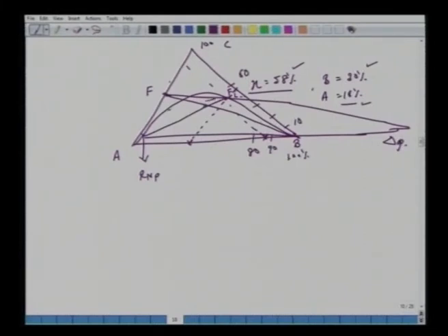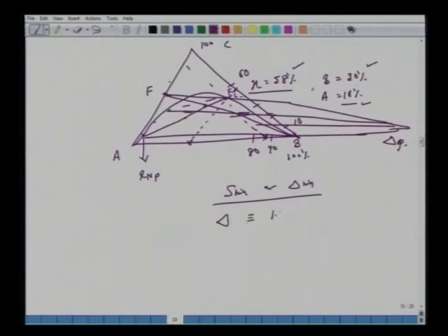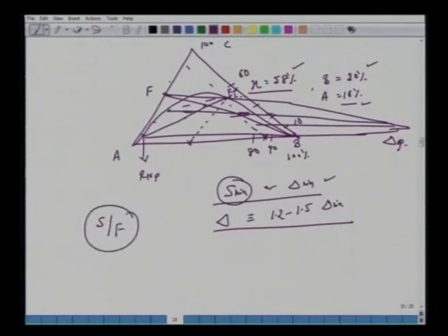Okay, so in this case the amount of solvent was given because the ratio of S to F was given to us. Although the absolute value of F was not given, we chose this basis of F. Why? Because again you go back to this mixing rule, we will have in the same ratios Ys into S equal to Xm into F plus S. Alright, so just choose a basis of 1 kg per hour, for which S is say 0.25 kg per hour, and then you can do this calculation here. Alright, so these are the examples we have chosen on countercurrent extractions.